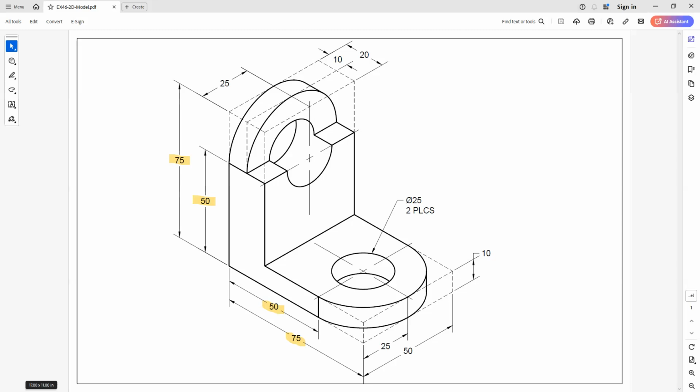On the right side view here, I'm going to color these a different color. I don't know if you could see it. Okay, there we go. I have to put at least these dimensions on there, right? Because these are the ones that are going to show on that view. I can also label this one, and this is going to be an optional one, right? I can either put this one on this view, or I can put it on the top view, either one. And then at a minimum, on my top view, I have to put these dimensions.